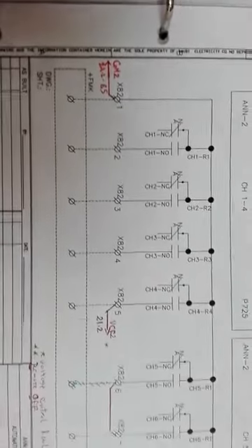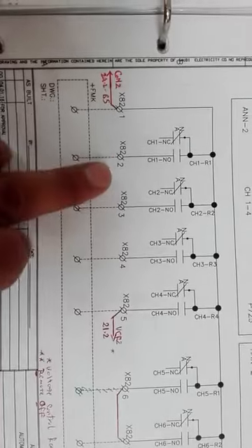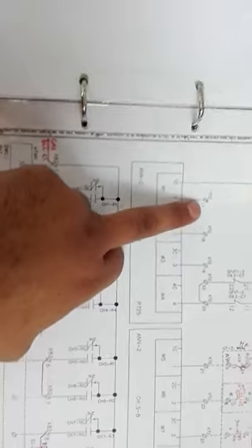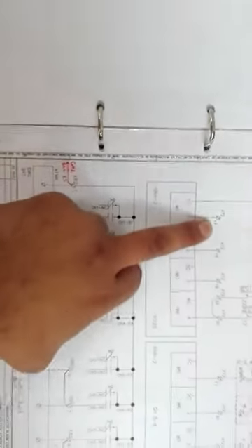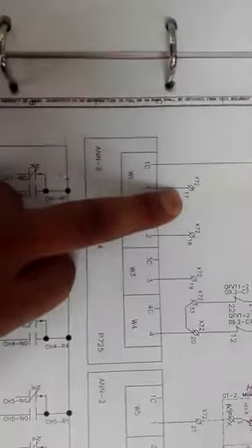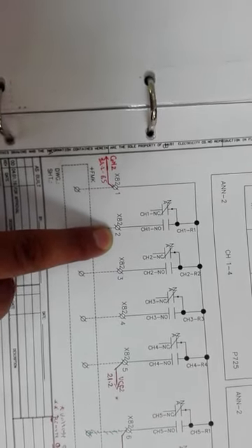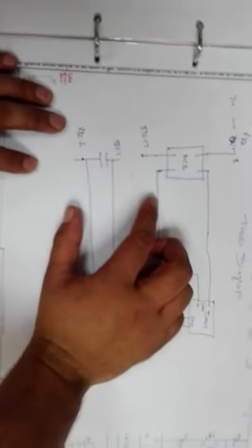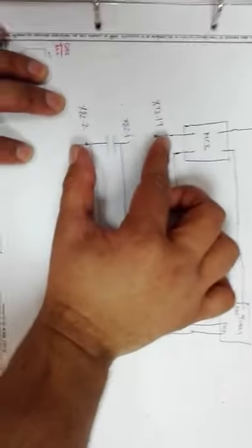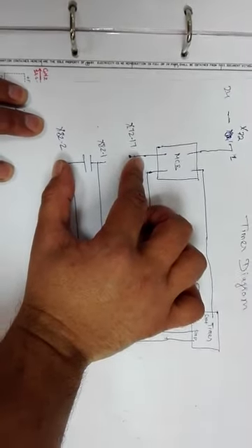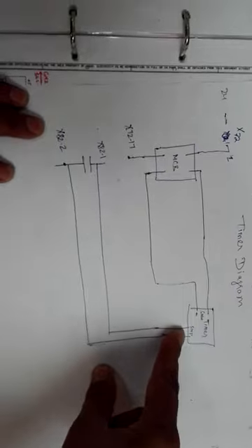And similarly for the output side, I will make the jumper between point number 17 and point X82.2. We will make the jumper to measure the time. Now for this time measurement test, we will make a jumper between these 2 points to start our circuits, to close the path and test the time.